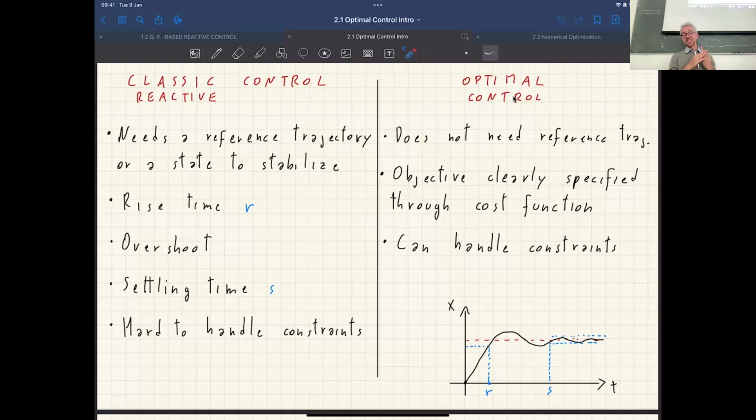But other constraints are very hard to handle with those tools, such as joint position limits. We have seen that they're hard to handle. And collision avoidance constraints. We haven't discussed much about them, but they're very hard to handle with reactive control methods. And the reason why they're hard is that in reactive control, you're only looking at what's going on right now, at this very moment in time. So you're reasoning in terms of accelerations, contact forces, joint torques, and that's it.